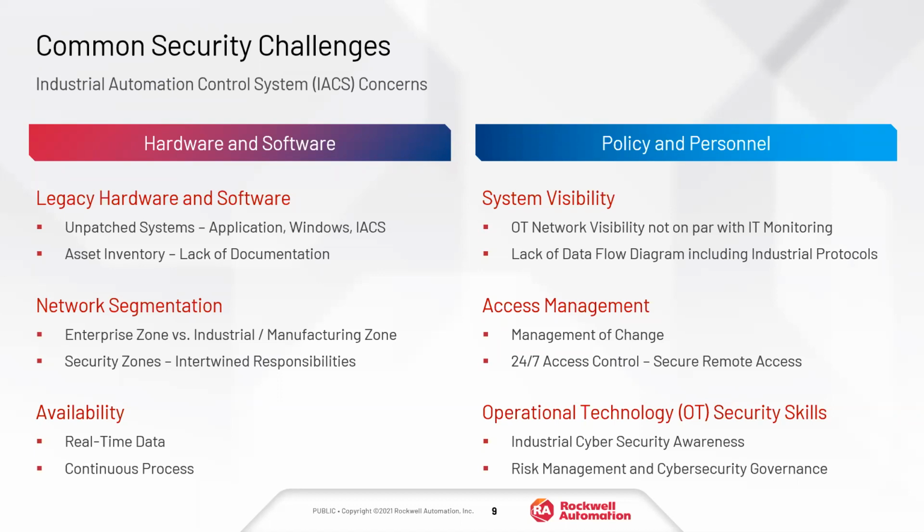The type of switches that are being used. Are we talking about managed switches versus unmanaged switches? How are those lined up in the system? Are we dealing with, especially on the Rockwell side, device level ring? Do we use parallel redundancy? Or are we just talking about a single compact logic simplex system? Is redundancy involved?